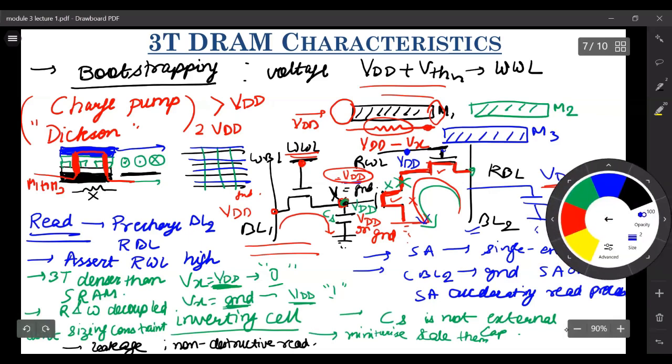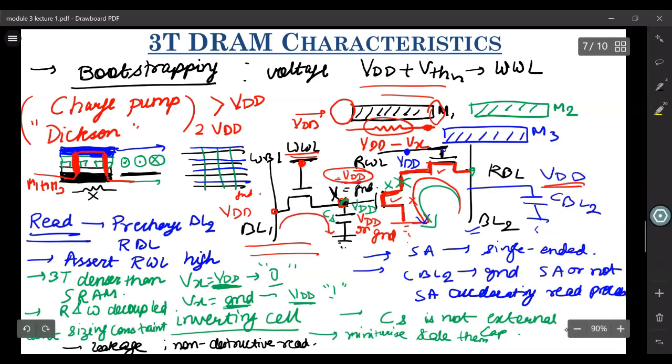Now what could be the disadvantages? It will have the same disadvantage that we talked about for the 8T SRAM cell. Since you have different bit lines for read and write, and different word lines for reading and writing, that would lead to routing complexity. But that is not very much here because you don't have to work with bit line and bit line bar, and again a word line, again a bit line just for reading the cell, like in the 8T SRAM cell.